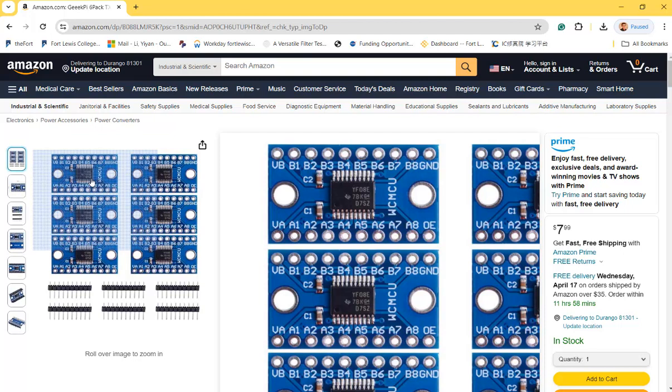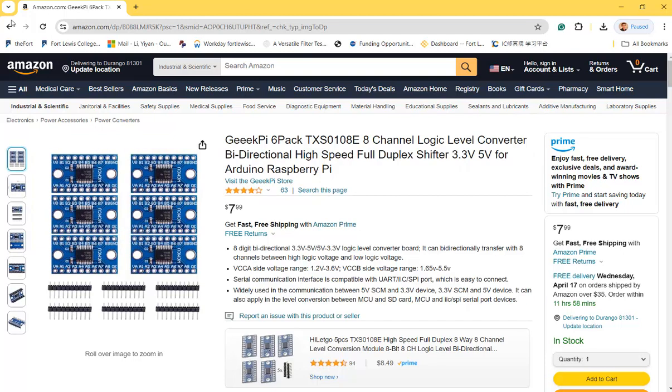And the OE should be some sort of enable. Just look at the data sheet, see if it's low active or high active. You probably need a voltage high, 5 volts, or 0 volts. Probably it's low, because low is common low, right? It could be it doesn't have a bar on the top, so I'm not really sure. It's easy to figure out by looking at the data sheet. So that's the level shifter